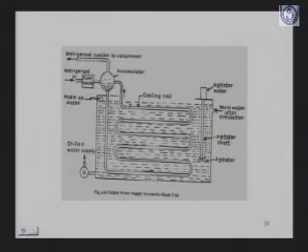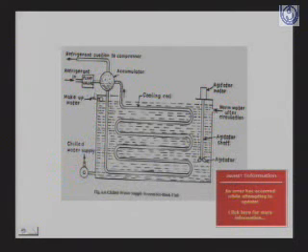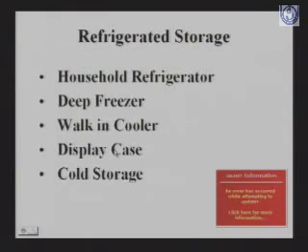So these evaporator coils will cool the water and make the chilled water, and then this chilled water is supplied to the pasteurizer, or to any other unit wherever it is required. And this is the makeup water. If you want to put in more water, it could be done.